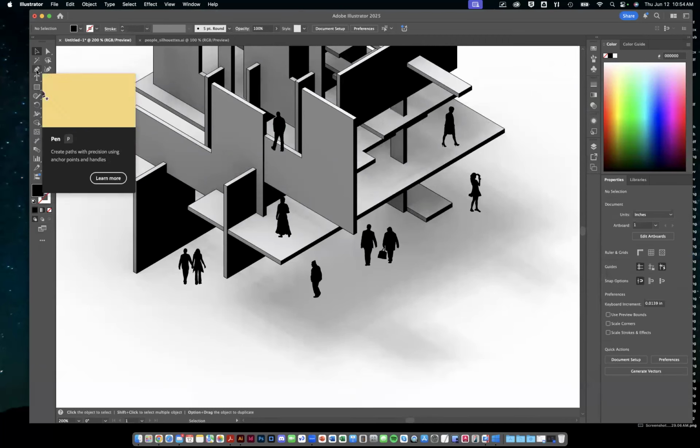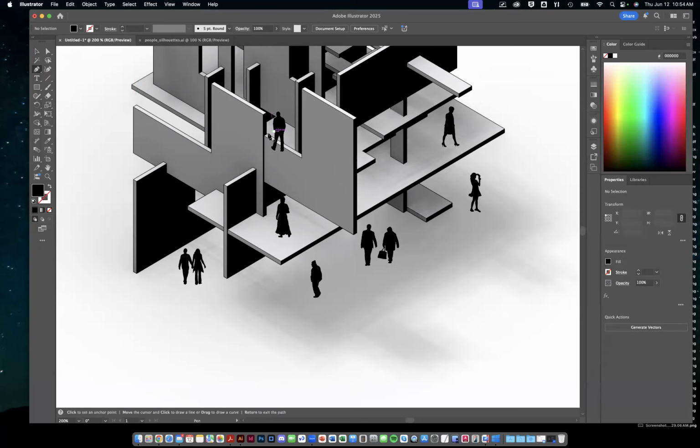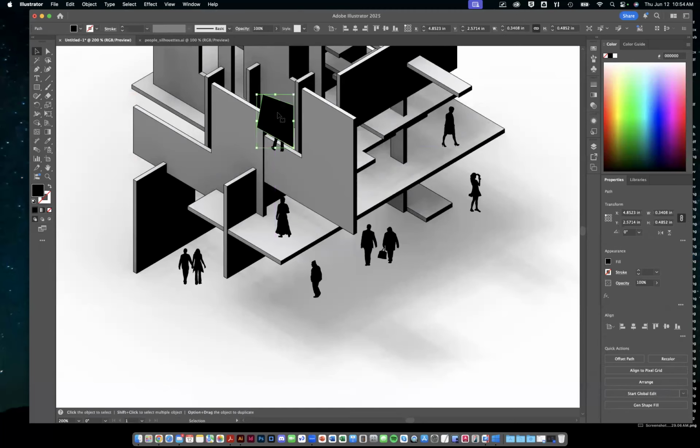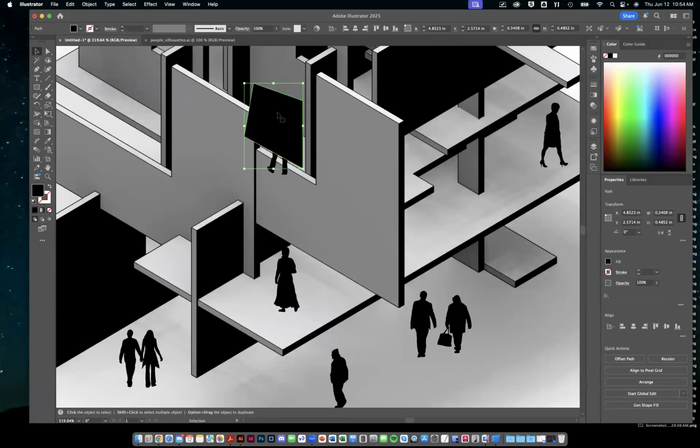what I'm going to do is make my own little shape here. I'm going to use the pen tool. I'm just going to go click, click, click, click, and I'm going to try to go back to that last one and end it. That's right. I haven't made a mask yet, but this is going to be our mask. I drew the shape with the pen tool, and now it's sitting exactly in the location of where I want that mask to be.